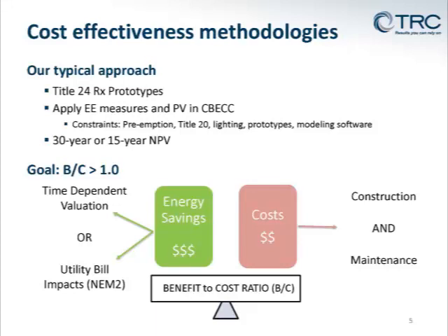So we looked at the savings estimated through that code enhancement report, and we translated those numbers to 2016, and we're going to say, well, if your building is in this climate zone, then we recommend taking off 10 to 15% of your domestic hot water load, and then resumming your total calculation, and then you'll have your new compliance margin. There are these workarounds that we would recommend to a certain jurisdiction that wants to adopt a compliance margin that's not currently achievable through the current model.